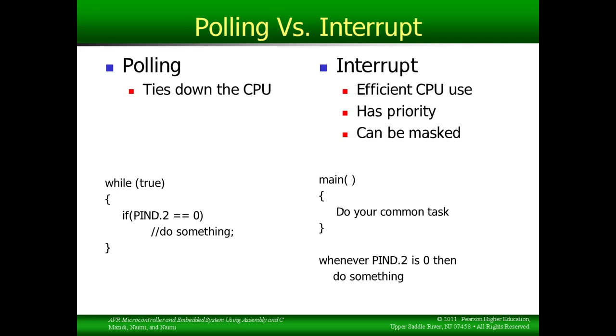Microcontrollers can service many different subsystems, and whenever a subsystem needs attention from the microcontroller, it can get service in one of two ways. Let me start over here with interrupts. The interrupt method would mean the subsystem sends a message to the microcontroller. The microcontroller would immediately stop what it's doing and deal with that subsystem. So it executes some special code to happen in the event of the subsystem needing service.